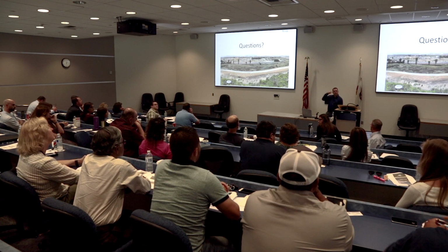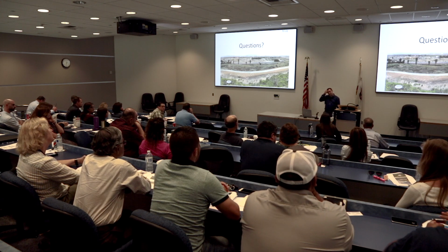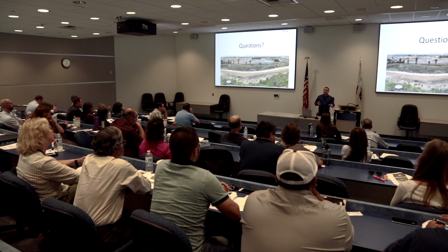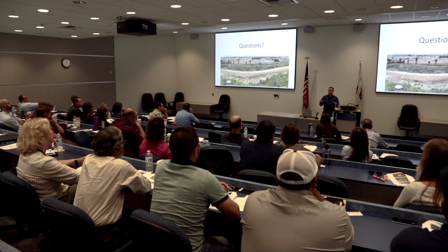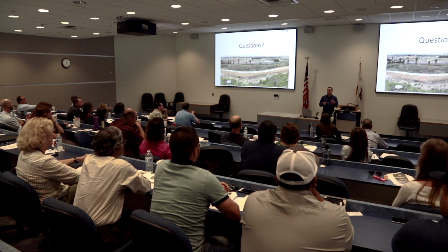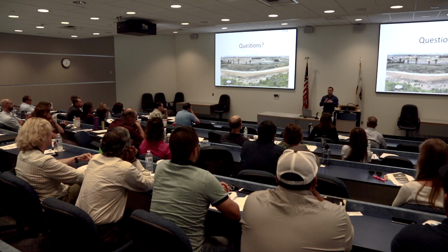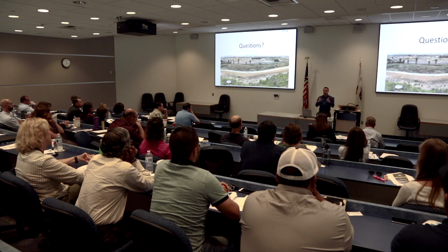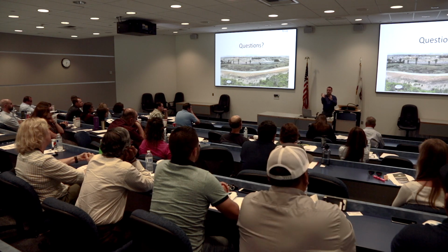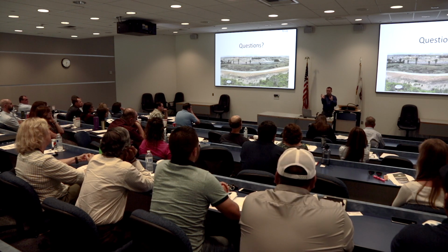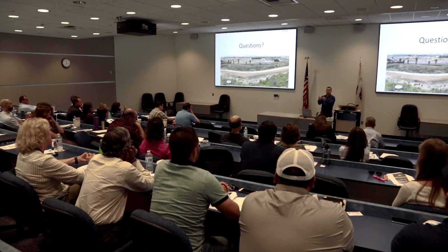Yeah. I guess the thing with the erosion control and sediment plans is, let's say your project is this big, right? So you have perimeter controls and all your stuff set up for this big area. But then they're only trying to get occupancy on a small portion, and this portion is the area that's now creating that flow to go online.